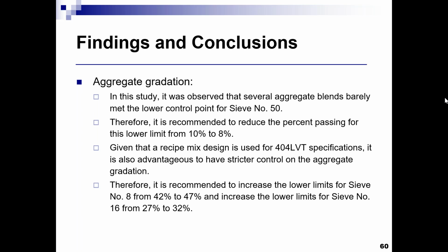Now, do you know of any heavily shaded roads that have been paved with 404 LVT? Yes, one of them was paved in Fayette County, close to the asphalt plant. Talking to Mr. Steve Luby, he told me that we took our chances and expected that we may see performance that is not consistent with the performance of the mix throughout the county. Driving at that location, it does look rougher than the other locations. So to answer your question, yes, it was installed in front of an asphalt plant in one of the counties. My recommendation is to avoid using it at a place where you expect this kind of heavy moving traffic.